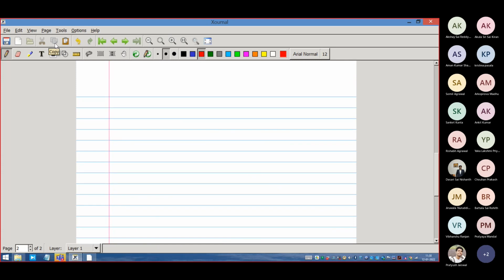So how do I do it? Again, I come back to the equation. The equation is now, the torque in the zone I wanted to operate. In the zone I wanted to operate, the torque developed is equal to, so the equivalent circuit is very simple. This is just R2 dash by S, right? So the torque is nothing but V by I square R2 dash by S. This is the power, I square R2 dash by S, right?